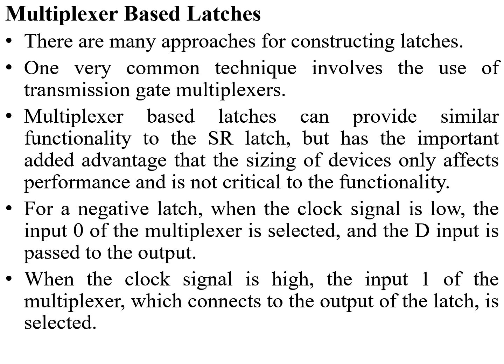Multiplexer-based latches. There are many approaches for constructing latches. One very common technique is the use of transmission gate multiplexers. Multiplexer-based latches can provide similar functionality to the SR latch but have the important added advantage that the sizing of the devices only affects the performance and is not critical to the functionality.